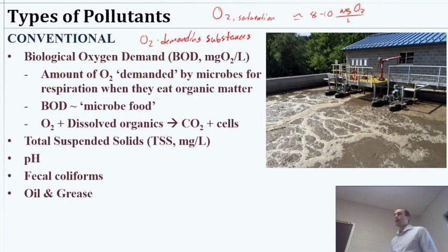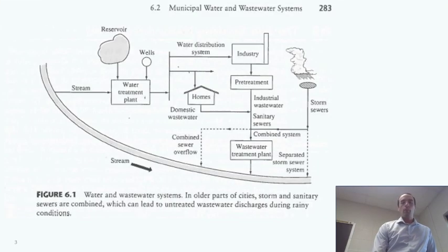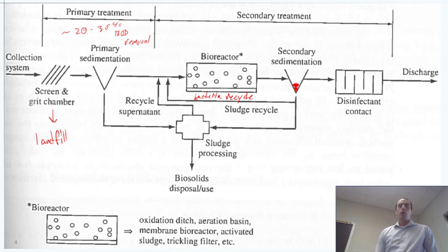But if you think about it, your primary treatment, so if we were to go all the way back up to look at our primary treatment here, if this is perhaps what the first wastewater treatment systems may have had, just primary treatment, well, the screen and grit chamber are not going to remove the oil and grease because it's liquid. The sedimentation is certainly not, it's going to be floating.